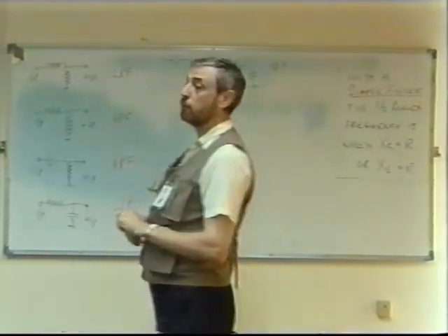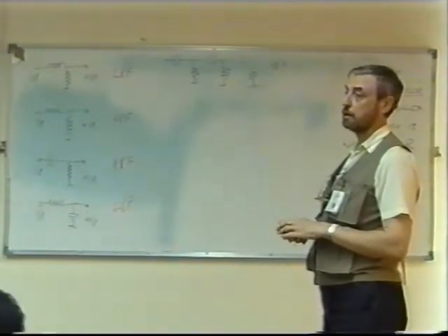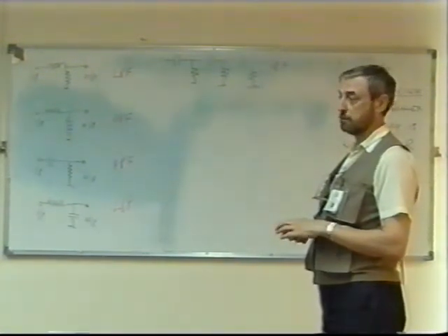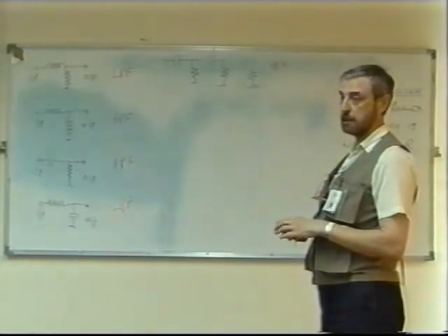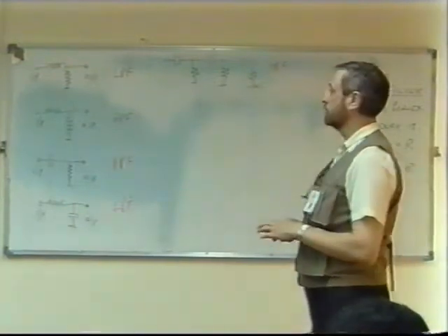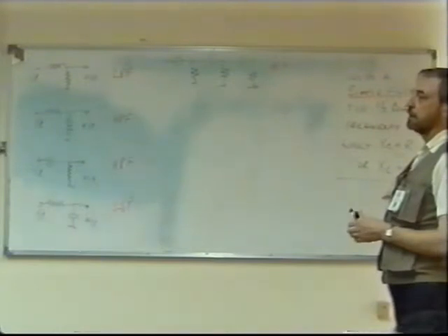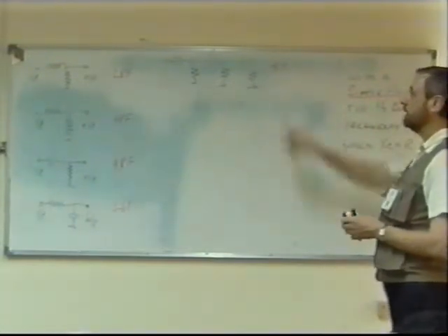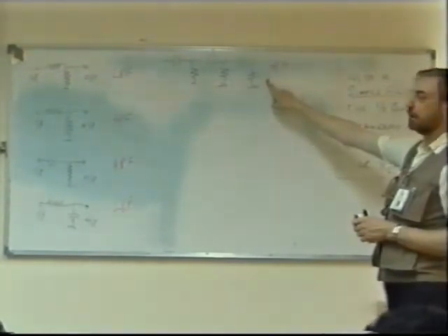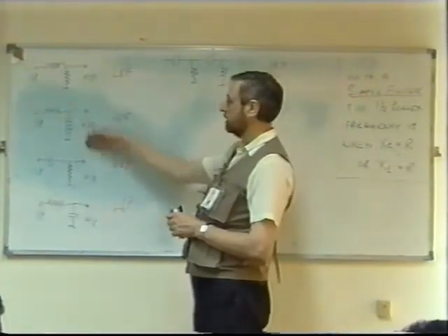You said it's a high-pass filter. And the other theorem that you gave us before: the cut-off frequency, the minus 3 dB, and the half power frequency, they're all the same, also the same name. Exactly, that doesn't make any difference on the type of filter. The difference only will be when calculating the cut-off. Imagine, here it would be more difficult to calculate what that frequency is going to be. Here it's much easier.